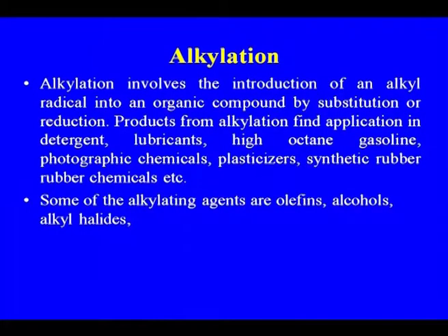Alkylation involves the introduction of an alkyl radical into an organic compound by substitution or addition. Products from alkylation find wide application in detergent, lubricants, high octane gasoline, photographic chemicals, plasticizer, synthetic rubber chemicals. Some of the alkylating agents are olefins, alcohols, alkyl halides. Here actually the alkylation process is now used in petroleum refining and the petrochemical industry both: alkylation for producing the high octane gasoline, and in the petrochemical industry for the manufacture of linear alkyl benzene, where alkylation of the benzene with the alkyl group gives the linear alkyl benzene.